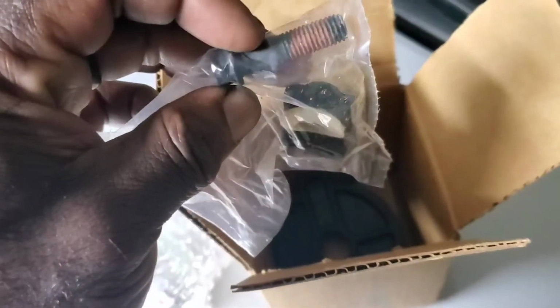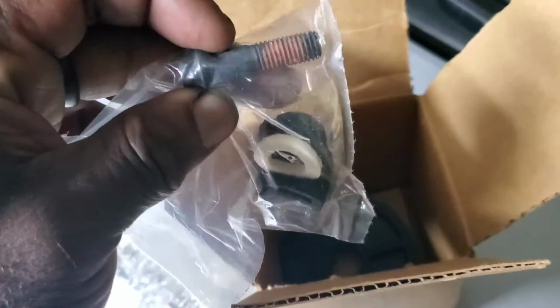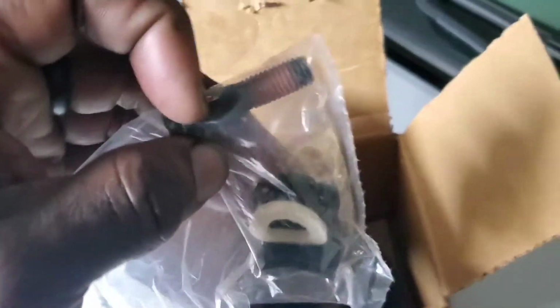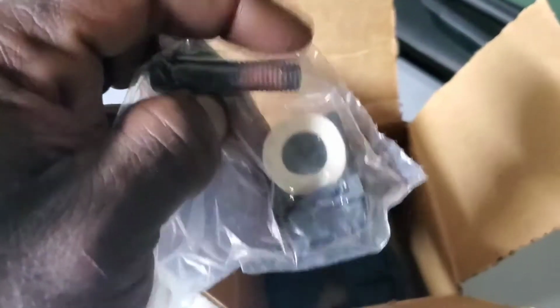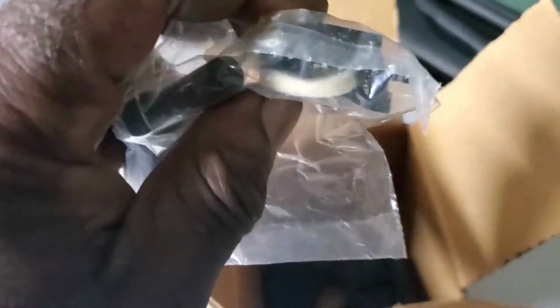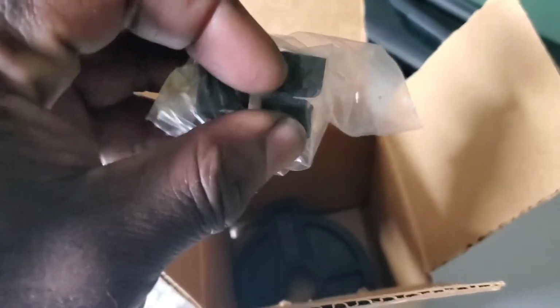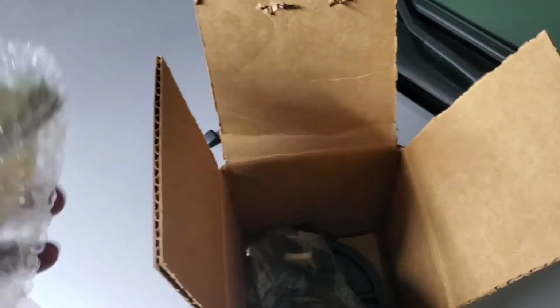According to the instructions in the service manual, there is a bolt that gets replaced down at the base of the intermediate shaft, where the U-joints are before they leave the cabin. You take that, discard that bolt, and replace it with this. There is this little absorbent ring that goes on the shaft to prevent grease from getting down into the sensor. And I do believe this cap is to cover the joint where the harness's wire comes out of the steering column.